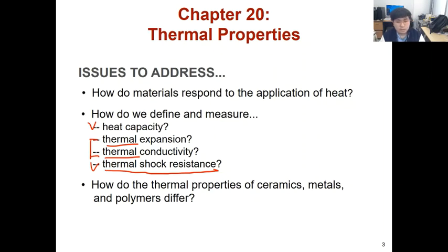It is because the temperature property is strongly related to atomic vibration motion. At 0 Kelvin, the atoms have a specific equilibrium distance, because we can decompose the interaction into a repulsive interaction and an attractive interaction between the atoms. When we combine the two effects, we have a specific equilibrium bond distance, which has a minimum energy, the equilibrium energy.